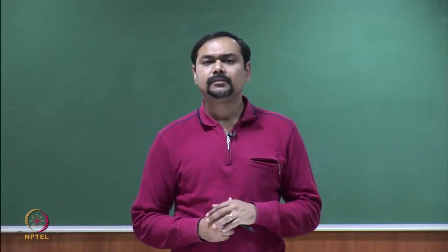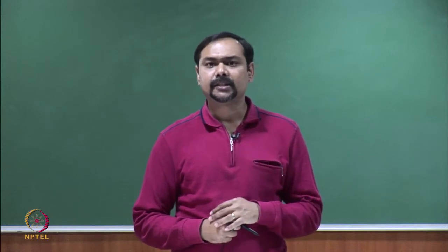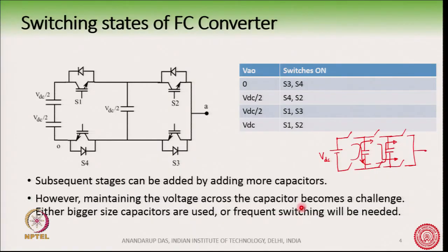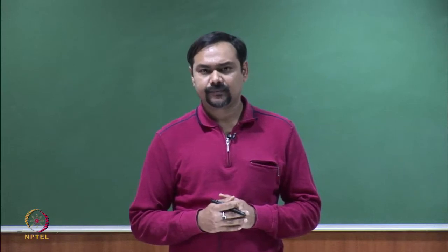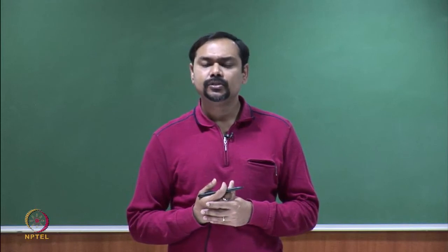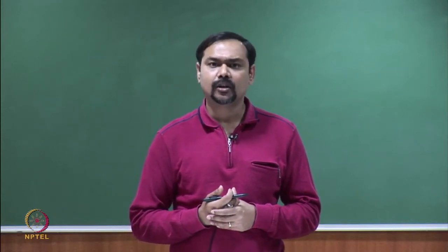The other way, if you want to keep a small size capacitor, is that frequent switching has to be done. So, you are continuously charging or discharging the capacitors, and the switching frequency of these switches increases. So, that is the compromise. Either you put a bigger capacitor or you increase the switching frequency and hence the switching losses in this converter.